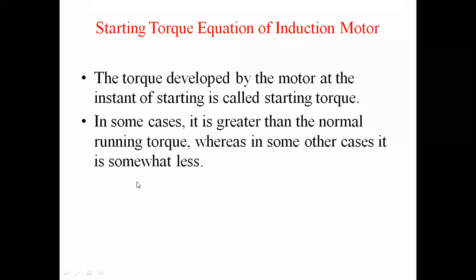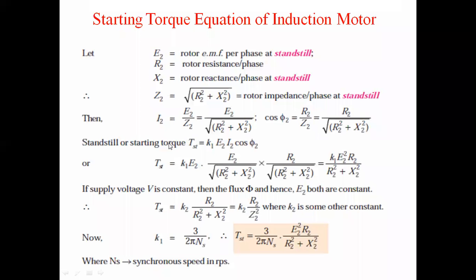Okay, so as stated in the name, starting torque is the torque which is developed by the motor at the instant of starting, that is, when the motor starts after we give the supply. Whatever torque is developed by the motor at the instant of starting is called the starting torque. In some cases it is greater than the normal running torque, whereas in other cases it is somewhat less than the running torque. So we will now look at the starting torque equation of the induction motor.